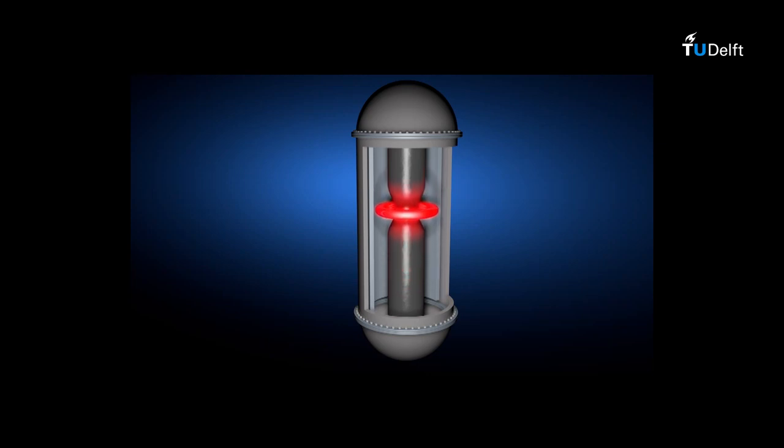During the process nowadays, nitrogen is intentionally added, which improves the control of micro defects and improves the mechanical strength of the wafers. The advantage of the float zone technique is that the molten silicon is not in contact with other materials like quartz, as in the Czochralski method. In the float zone process, the molten silicon is only in contact with the inert gas like argon.